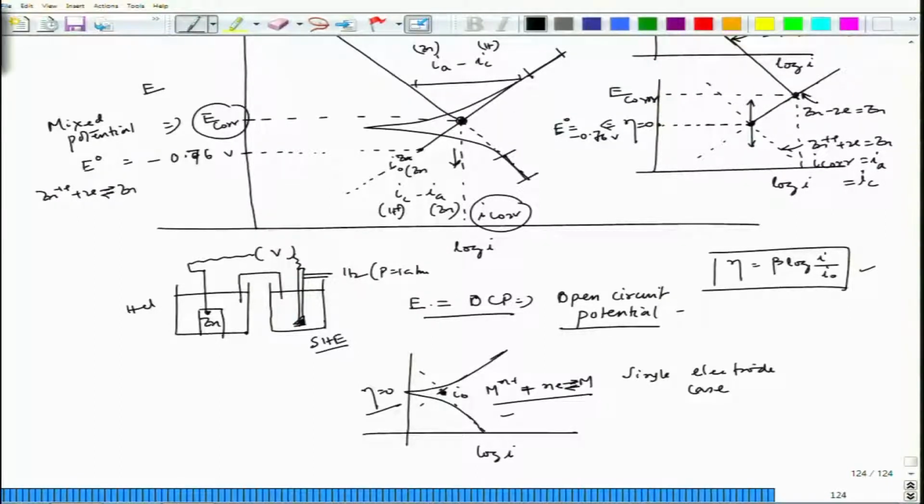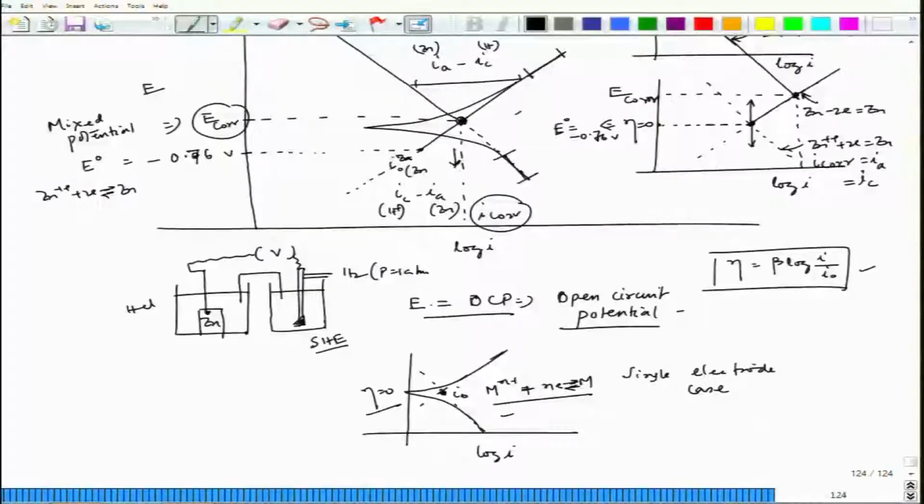This particular part will come in corrosion part 2, but since we have considered this, we are just explaining a little bit. So, if I look at the mixed potential theory in a nutshell, we could see that the new potential is achieved, and that new potential is achieved due to the polarization of those partial reactions. One would definitely be cathodic and another one would definitely be anodic polarization, in this simple situation where this entire reaction is divided into two parts.